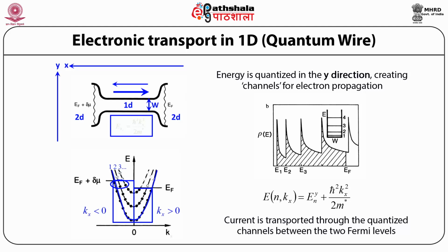But what if we reduce the length to a very small dimension, let us say 0? Will the resistance tend to 0 and it becomes a superconductor? Conventionally, when an electron passes through a solid, it follows a random path, traveling in one direction for a short interval of time and then scattered in another direction. This is called diffusive transport.